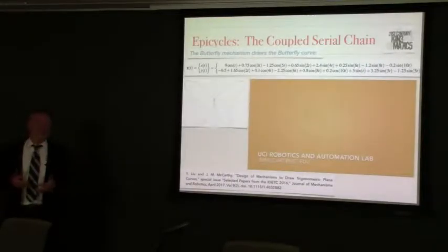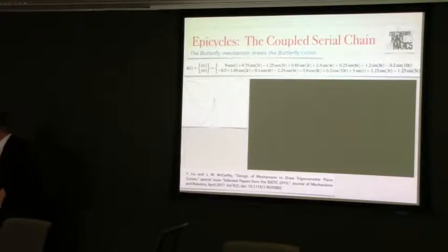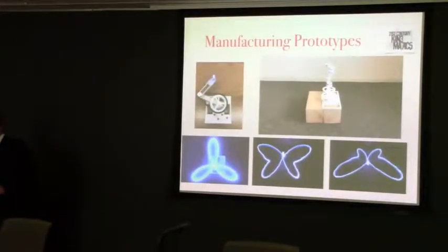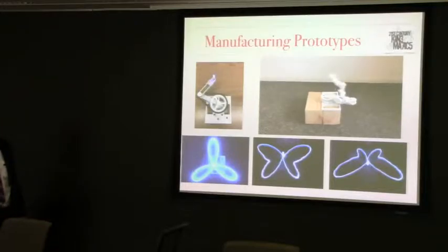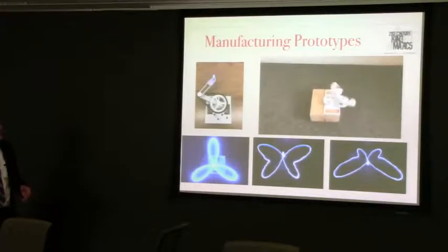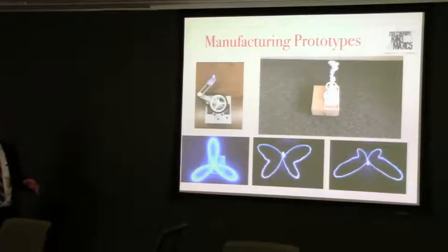It turns out that these gear ratios are in many cases non-standard, and therefore the best thing we could do is actually try to build them with additive manufacturing. So here it is. That's it, moving. We did the best we could. We matched all the gears as best we could. We made the ABS as stiff as we could, but just the slightest little bit of manufacturing error introduces backlash. What you're seeing is, the thing is about this tall. It just gets a little bit of wobble, not a lot, but just enough.